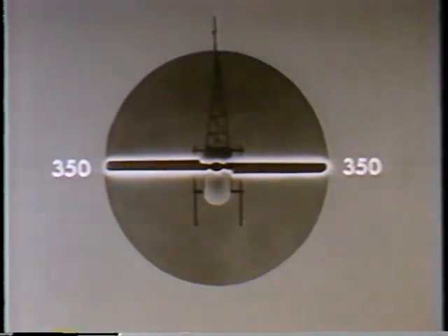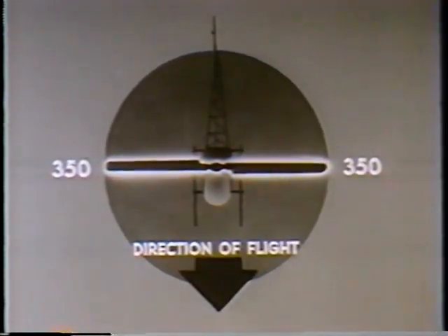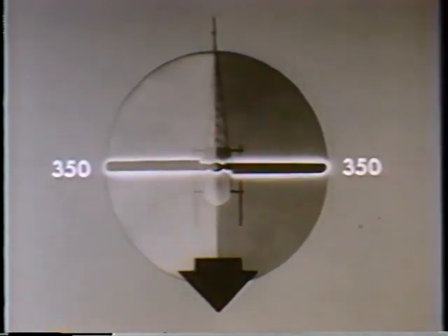During vertical flight, of course, the blades will produce the same amount of lift at all times, since the air will pass over them at the same speed during their entire cycle of rotation. But the moment the helicopter starts to move in any direction horizontally, a dissymmetry of lift is produced. That is, the blade advancing through the unshaded area will begin to produce more lift than the blade retreating through the shaded area.